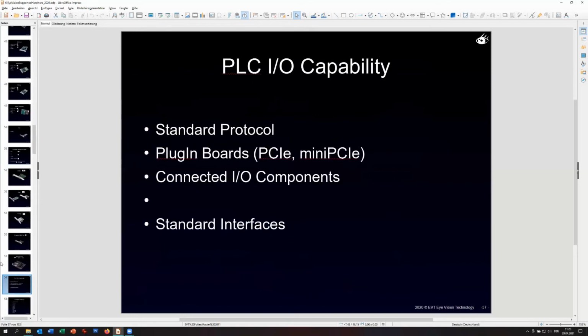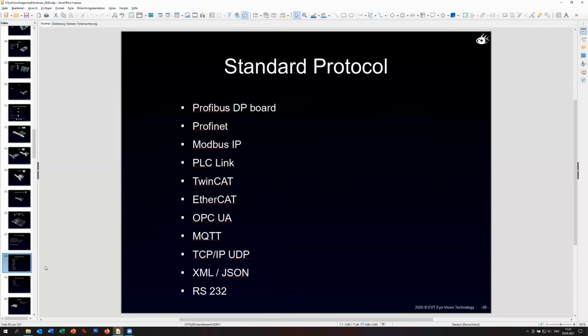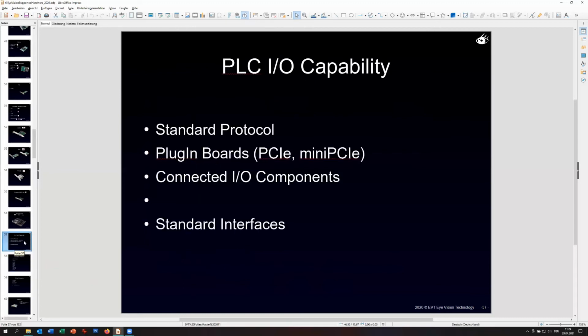Of course, machine vision always means I/O capability, whether digital I/O or any bus system. This is independent of whether you do 2D, thermal, or 3D machine vision. What's interesting is if you need I/O, especially for 1D machine vision, these are line scan cameras. If you have a very stable production process and a stable movement of your parts, then you can run the line scan camera free.